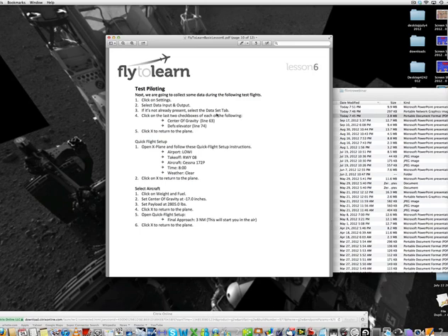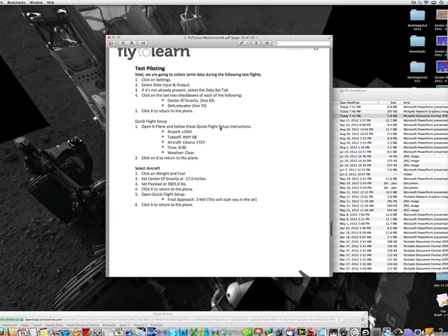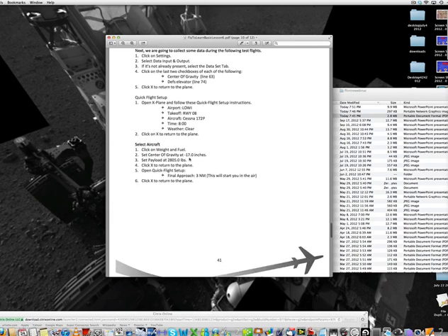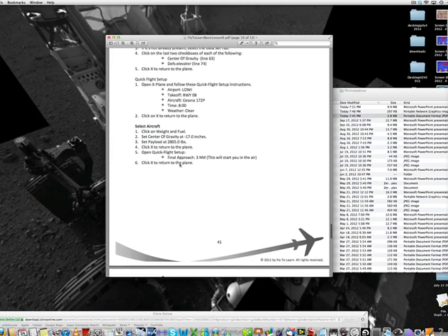They'll go to settings. They want to know the center of gravity. You want to get that line. And then also the deflection for elevators will tell you in line 74. That's the data you're going to check. This one's a little bit different. All you do is look at the cockpit. You don't have to graph it. And then if you notice, we set the center of gravity at negative 17 inches, which is pretty extreme. And we increase the payload a little bit there.